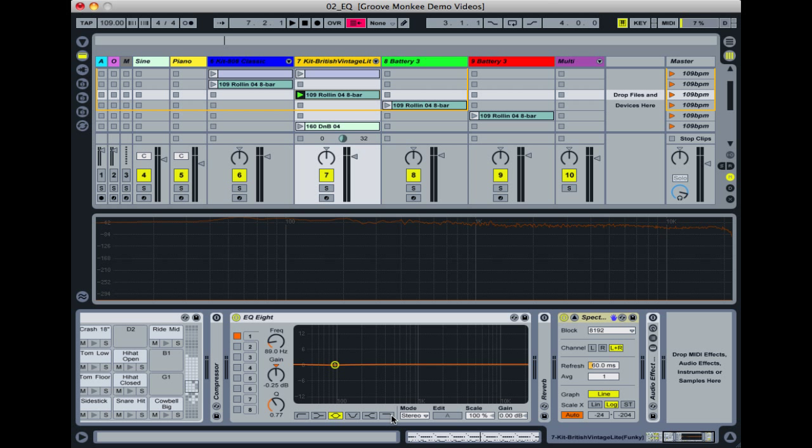And in most cases, you'll have a choice between the different filter types. First of all, the very first default type is probably the most common. It's called parametric EQ or bell curve. Now, you can't really tell from looking at this picture. This is actually a bell curve pointing both ways. Some EQs will only show it going upwards, but it can also go down as well. That's because you can either boost or cut with this particular filter type.